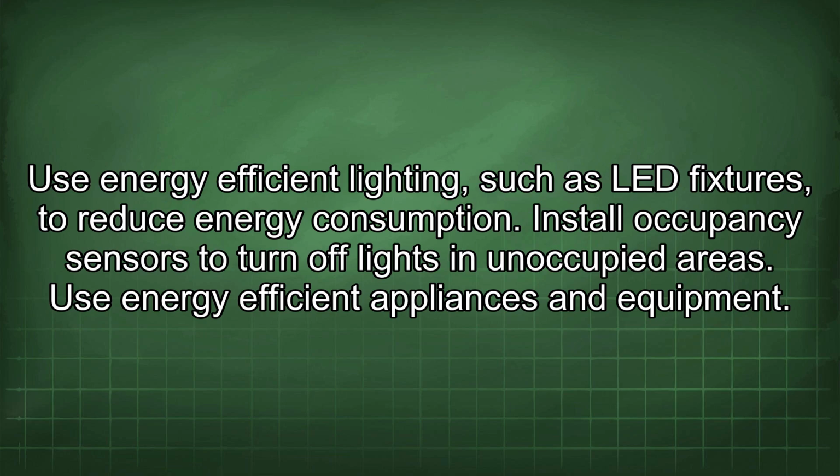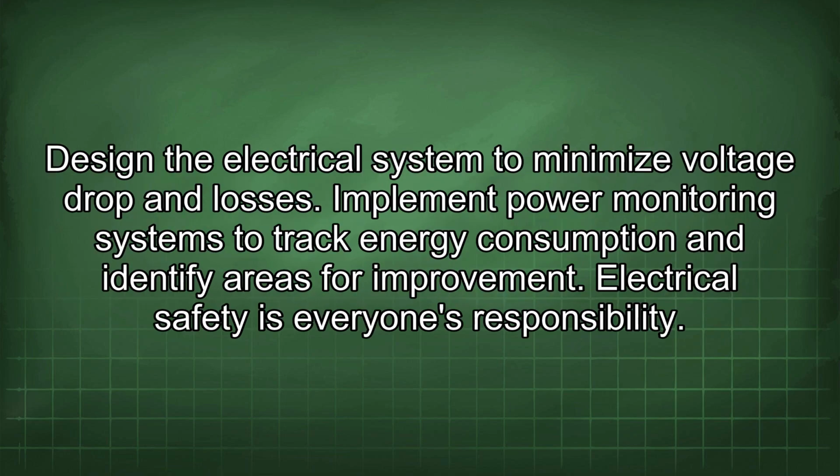Install occupancy sensors to turn off lights in unoccupied areas. Use energy-efficient appliances and equipment. Design the electrical system to minimize voltage drop and losses. Implement power monitoring systems to track energy consumption and identify areas for improvement. Electrical safety is everyone's responsibility.